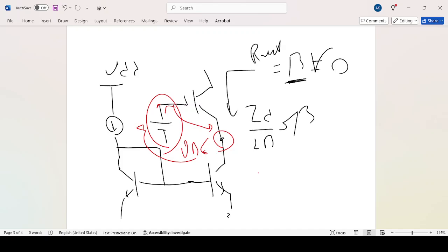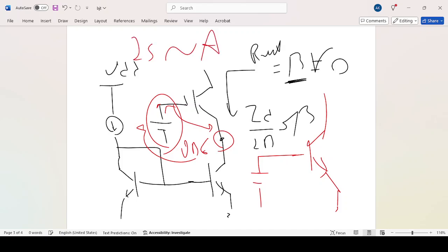So I forgot to mention this, that if you have a BJT like this, one thing that is happening is that IS has a relation with the area of the transistor and with the temperature, so it changes drastically when you bias this.